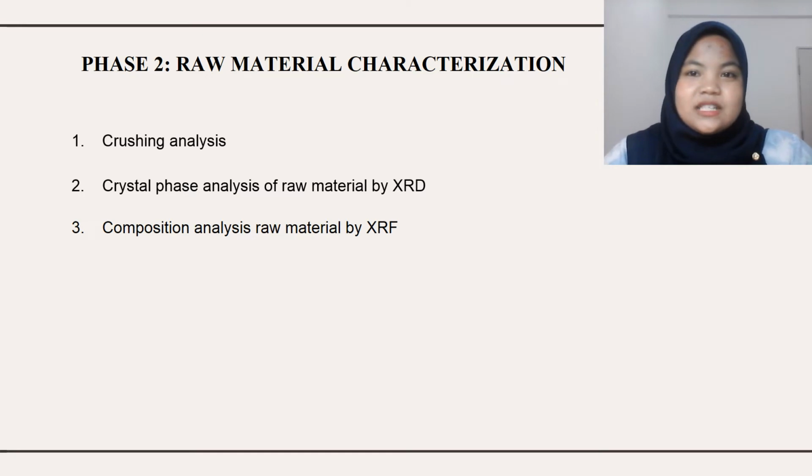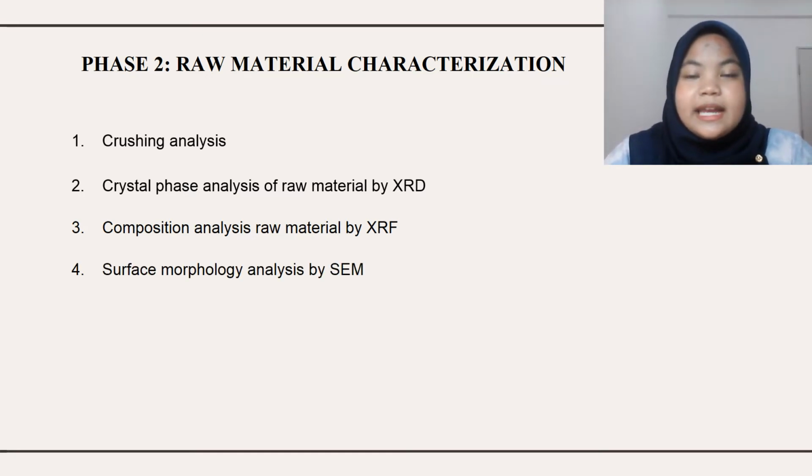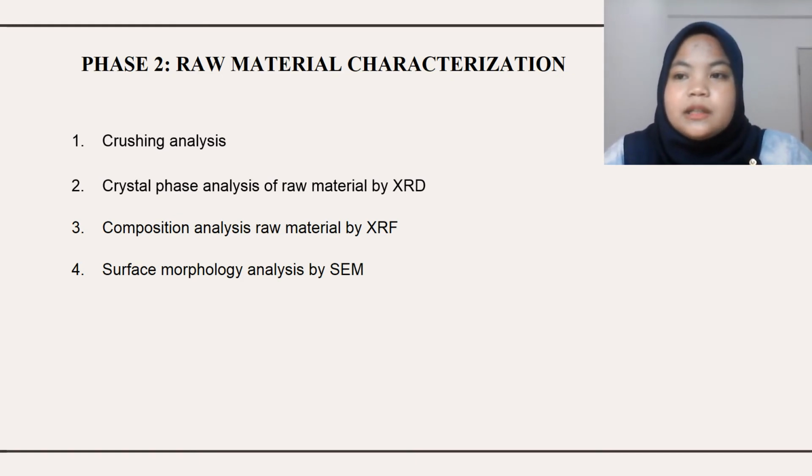The fourth is surface morphology analysis by SEM, the scanning electron microscope. A morphological analysis of a deposit, for example, reveals the properties of the liquid phase responsible for the creation of necks, which is particle-to-particle bonding between deposited particles.